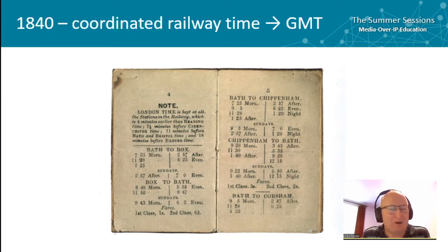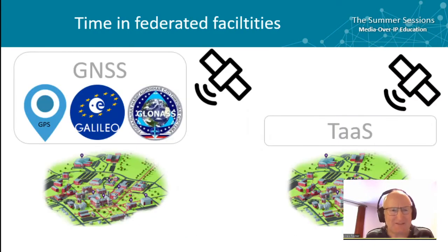If we move on a slide and look at this next thing, we're in a similar manner needing to think about common time in different locations, because the whole ethos that we've built the 2110 suite upon and our facility timing is effectively having a common timing reference, which is obviously very easy to do within a facility. But as we move across facilities, there's going to be some phase offset due to the sheer propagation time over the wide area network, but it's important that our facilities are frequency locked.